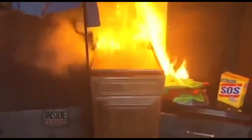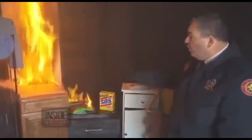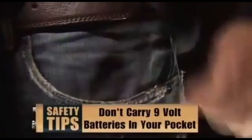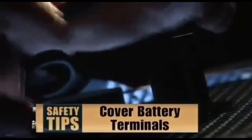You can see a simple fire in a kitchen drawer, how quickly it can extend to involve that whole cabinet and the upper cabinets and cause amazing devastation very quickly. There are steps you can take to avoid a fire. First, always keep the batteries in their packages before use. Second, don't carry 9-volt batteries in your pocket. Keys and coins can short the battery. And third, cover the terminals of all loose batteries with a...